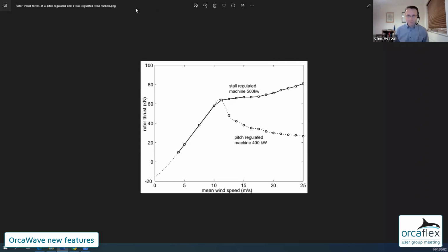Thanks, James. Yeah, we've just got one question on OrcaWave. The question is about Morison elements, and it says if we have them in OrcaWave, don't we need to add the Morison elements in OrcaFlex as well? So yes is the answer to that question. In terms of the programs, as I said, we've kept them in step, and the Morison elements in the two programs have identical functionality. And if you run a case in OrcaWave that has Morison elements like the one I showed you, and you import that into OrcaFlex,